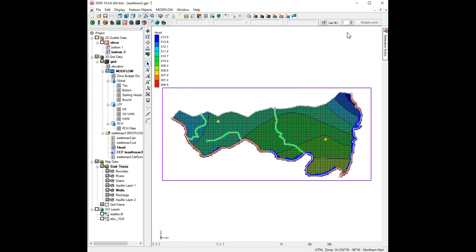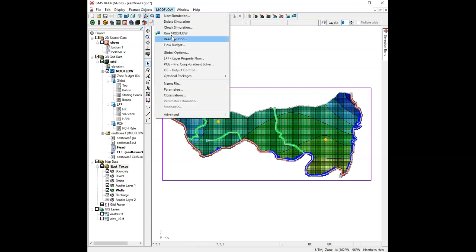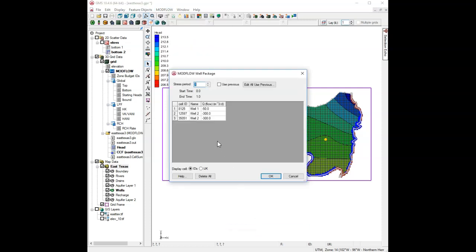Now it puts a well in both layers, and if we go to the well package dialog, you'll see that, well, I take that back, it puts the entire pumping rate in each of those two wells. So it doesn't partition it. I was thinking of a different scenario. I think with the screens it partitions it according to the overlap, but when you just do layer 1 to layer 2, it puts that same pumping rate in both layers.